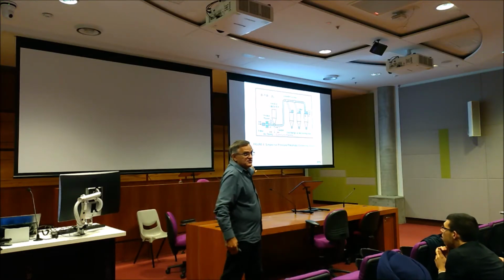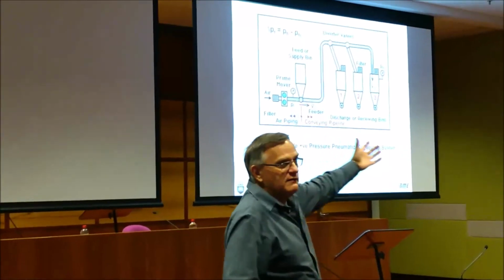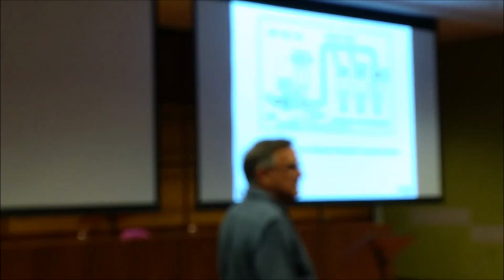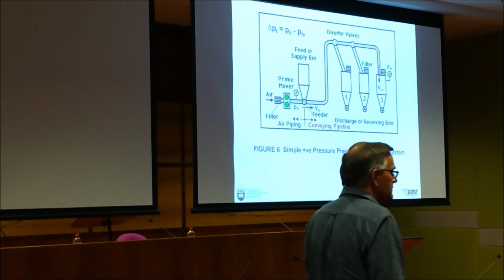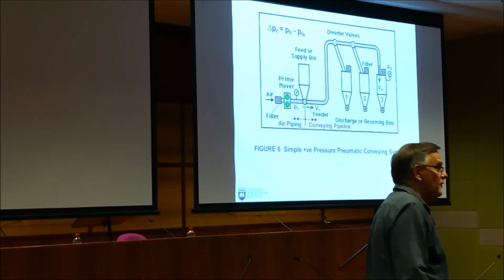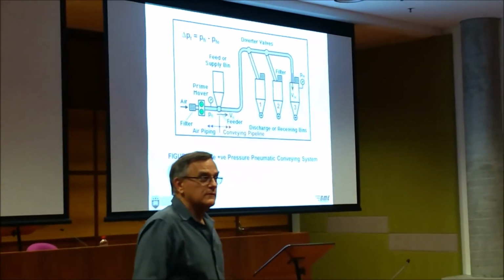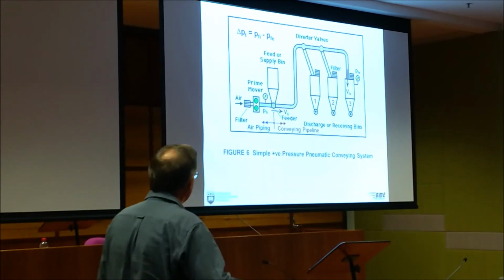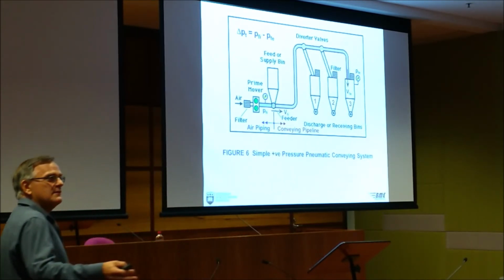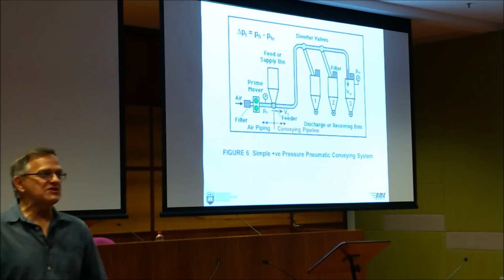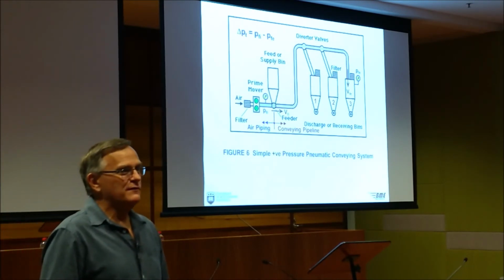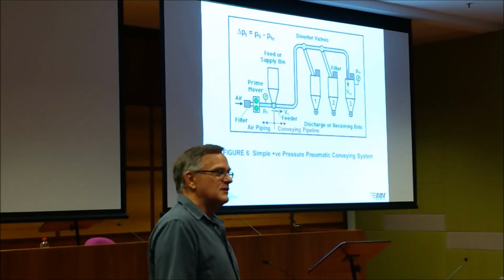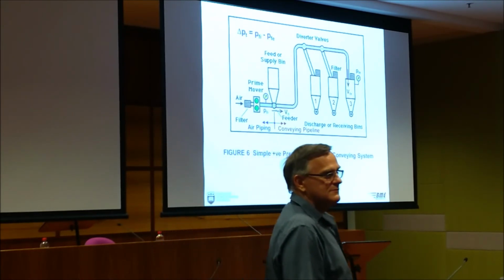If this is a hydraulic system, which one's bigger, VFI or VFE? Hydraulic system, liquid. Sorry? VFI. The same. There's three options again, but I won't go through those. It's the same, because in hydraulic systems, liquid's incompressible. So VFI equals VFE, velocity of fluid. It's constant. In pneumatic conveying, it's never constant.